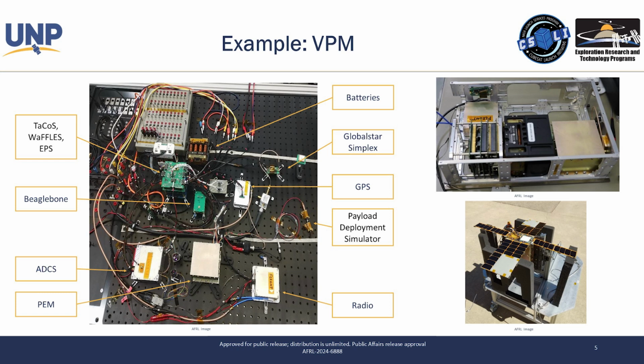So this is called the flat-sat phase of integration and test, at least for satellites, where you can see all of the interfaces literally laid out in front of you. It's not all folded up into a box. So it's a really great way, like your system block diagram that you might be working on very early on, where you say, okay, the batteries are going to connect to the regulators, are going to connect to the switches, are going to connect to the radio, et cetera, et cetera. You literally can physically lay that out as close as possible to your diagram, so everything sort of logically flows as you do your engineering.